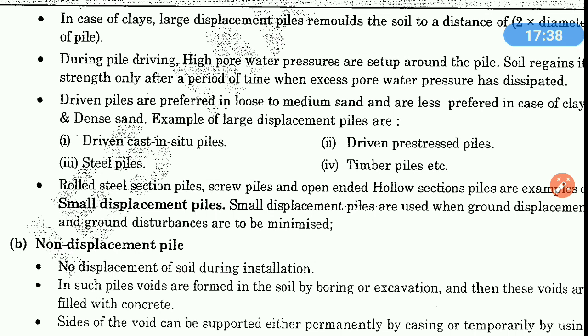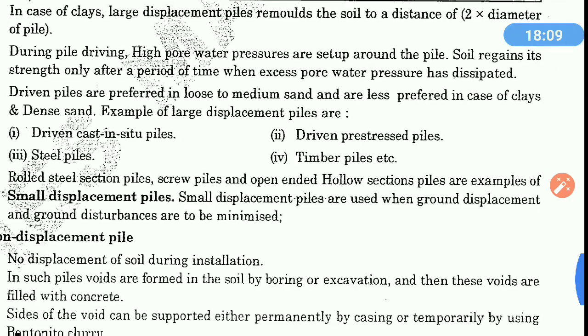So due to the excess pore water pressure, just after the installation of the pile, the soil may lose some amount of bearing strength or shearing resistance, but after some time when the excess pore water gets dissipated, the soil regains the strength, shearing strength or bearing strength, more than the previous one. Driven piles are preferred in loose to medium sand and are less preferred in case of clay and dense sand.